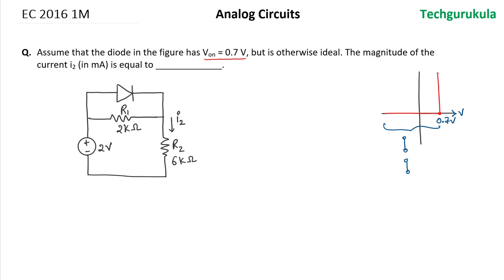because the current flowing through it is zero or negligible. But when the voltage across the diode becomes 0.7 or slightly higher, then the diode is modeled as an ideal diode in series with a cut-in voltage 0.7 volts. But in fact, the ideal diode will be a short circuit in that scenario, and we have only the voltage source representation of cut-in voltage.